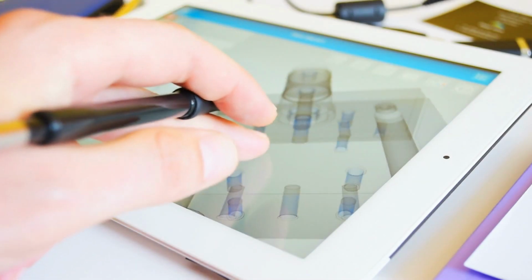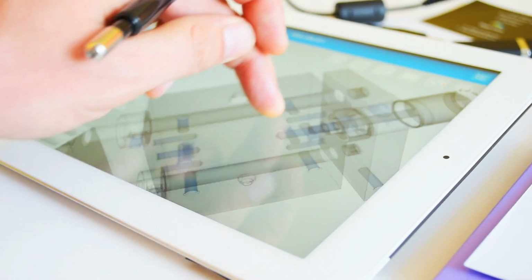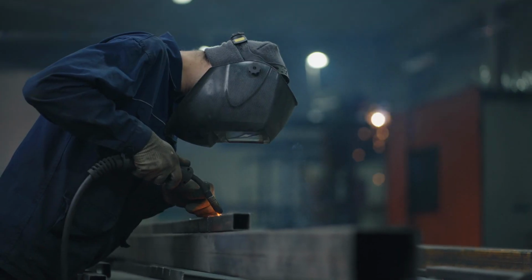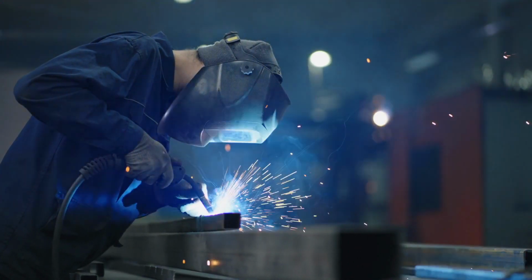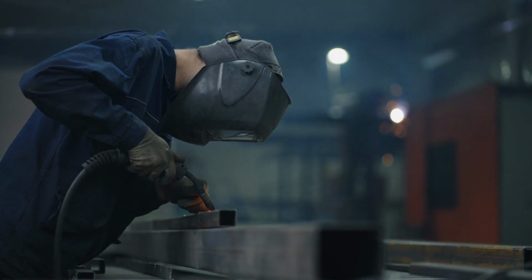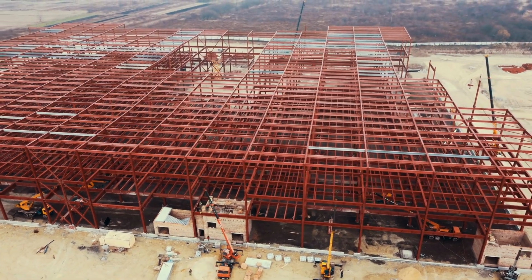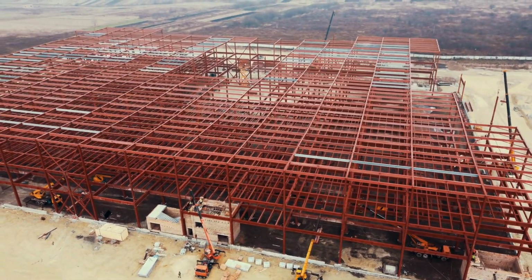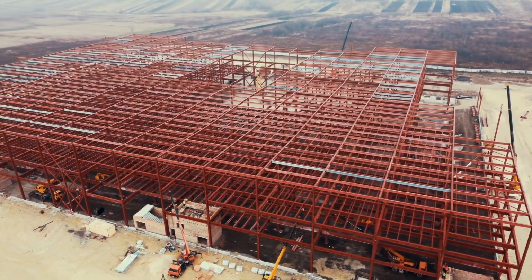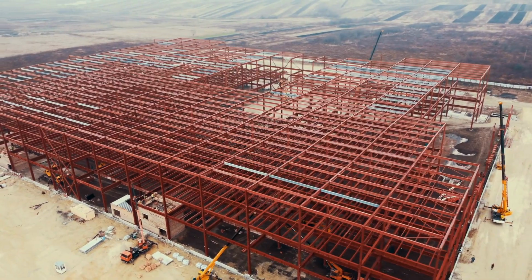And similar to shop drawings are fabrication drawings. Fabrication drawings are also produced by the company who will actually do the work, but often come after shop drawings are approved. Fabrication drawings are related to work that takes place off-site in order to fabricate or manufacture completed products that will then be transported to the site and installed. Said another way, items depicted on fabrication drawings will become part of the finished work and are supposed to be fabricated to the exact dimensions and specifications of what these drawings show once approved.